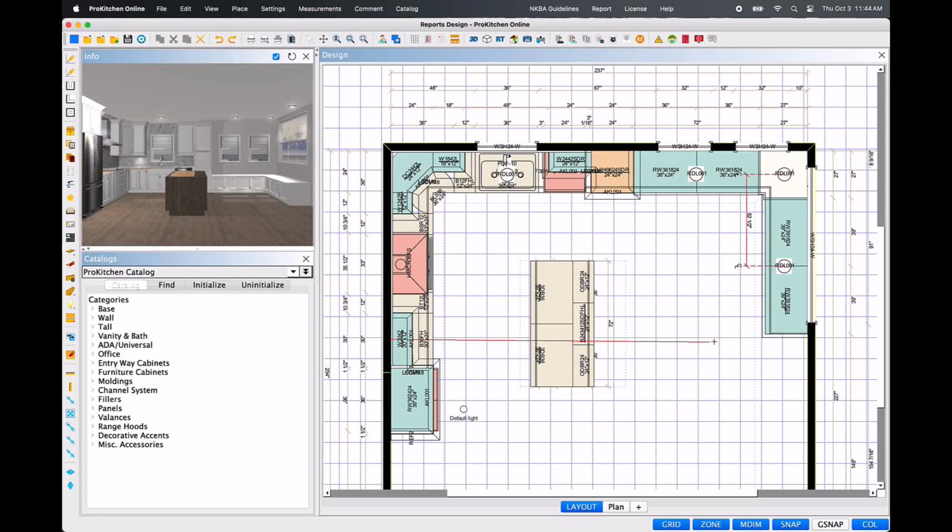Note: this line must be drawn in a straight line. Otherwise, the dimensions displayed will populate to reflect the distance along the angle at which it was drawn. Continue to drag the mouse over all the distances you wish to be displayed. Once the mouse is at the desired endpoint, left-click once more to create the dimension line. As you can see, now all the distances and dimensions along the newly placed dimension line are displayed. Multi-dim is a static dimension line and cannot be altered unless we move objects manually.